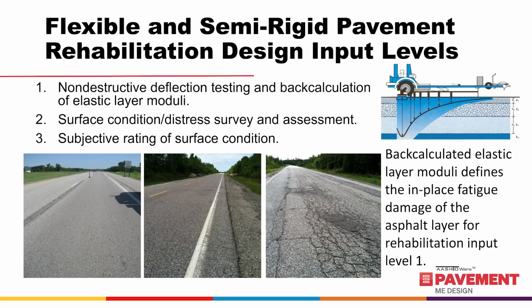There are different input levels for flexible and semi-rigid pavement rehabilitation design. Level 1 needs non-destructive deflection testing and back calculation of elastic layer moduli. Back-calculated elastic layer moduli defines the in-place fatigue damage of the asphalt layer for rehabilitation input Level 1. The concept for use in rehabilitation design is to associate the back-calculated elastic layer modulus of the asphalt layer to the amount of bottom-up fatigue cracking you can see at the surface.